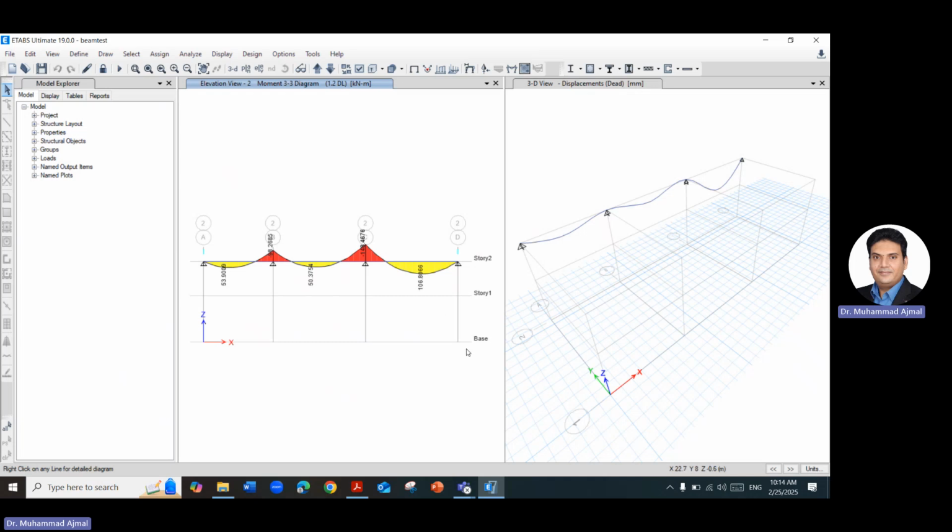Now, if you can get these maximum moments, what is the next task after your analysis? Just take these moments and go to the manual calculation, do the design. Maximum moment is there. So calculate steel ratio and then find spacing, all those, because it is the only issue which you are facing in the continuous. Now, this is only with the dead load.